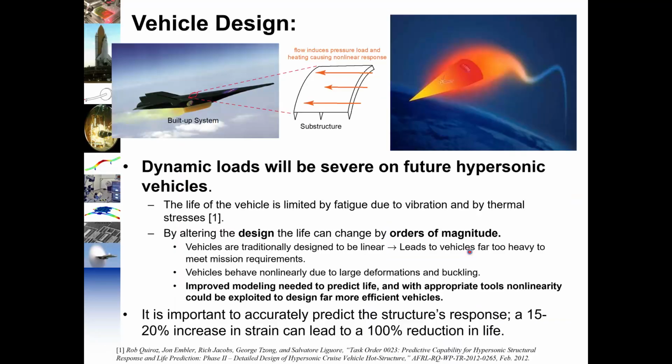And when you get to those kind of levels, you get really large loads on panels, and that can induce a nonlinearity. And those are important because the stresses depend on vibration amplitude, and a relatively small change in the stress, when we're talking about fatigue, can cause a huge reduction in life. These fatigue curves are usually on a log-log scale. And so when you get to this threshold of high stress, it can really have a severe impact on life.